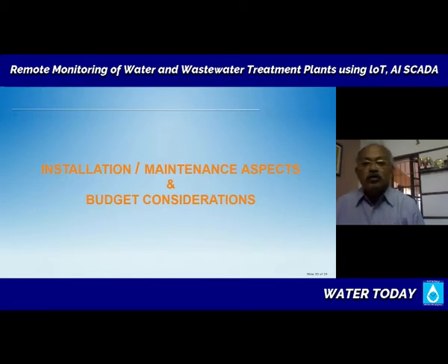We cannot go to the municipality and say, can you shut down this pipe? I want to install a meter. With them, all the meters have to be installed with very, very high accuracy measurement, completely online. Even pipes that are as large as 3 meters to the smallest pipe, which is, I think, 300 mm. So all these pipes, you have to install the meters without shutting the pipe.